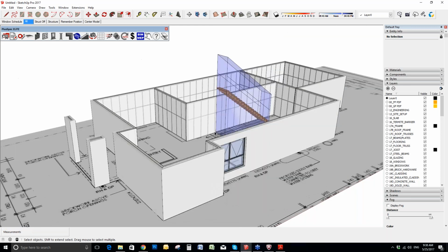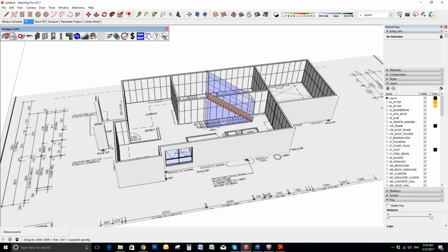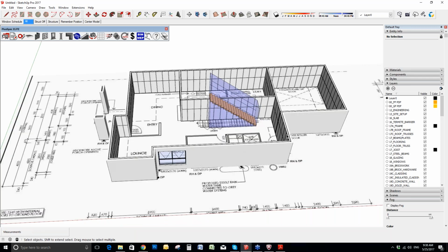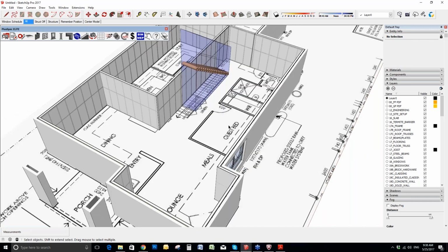All of these things have been captured. If you've got paint that you're using, you can even paint your different materials. So right now, if I was to click on my takeoff, on my quantities, I've got a 100% accurate takeoff to what I have drawn. If there's other items like the windows and doors and other walls that I haven't done, I know my takeoff isn't complete, and very quickly and easily I can see that it's not complete. I know where I'm at in my takeoff.